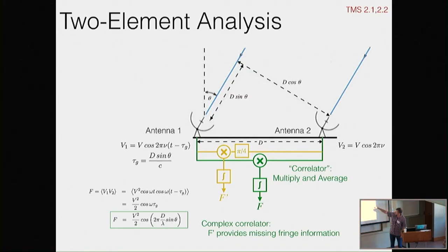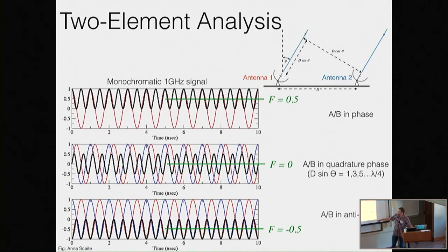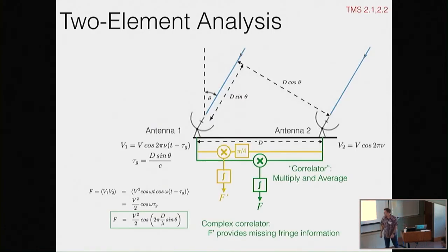And we take our signals and delay one of them by 90 degrees and make this product again so that this failure mode doesn't happen. We're effectively shifting one of these by 90 degrees so that we're always capturing the full signal. And we can express that as a complex number as a mathematical convenience, and it is quite a convenience, but the voltages are still real on the wires.